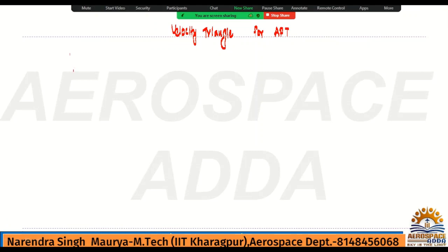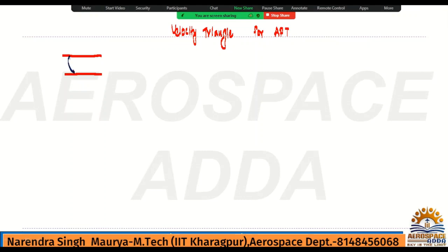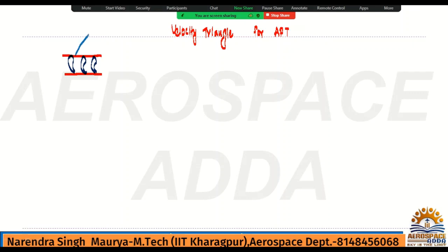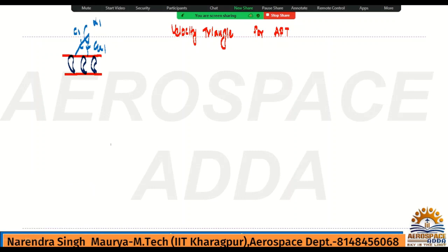So like here you had seen, suppose this is the blade here, see. Okay, this is the blade, and if you check the flow will be, obviously inlet will be the absolute flow. This is C1, and this will be CA1, and this angle will be alpha 1. Okay, and this is nothing but nozzle, or you can say stator. Then this flow will go to the next, which is nothing but you can say it's an inlet for the rotor. So this is the inlet for the rotor.